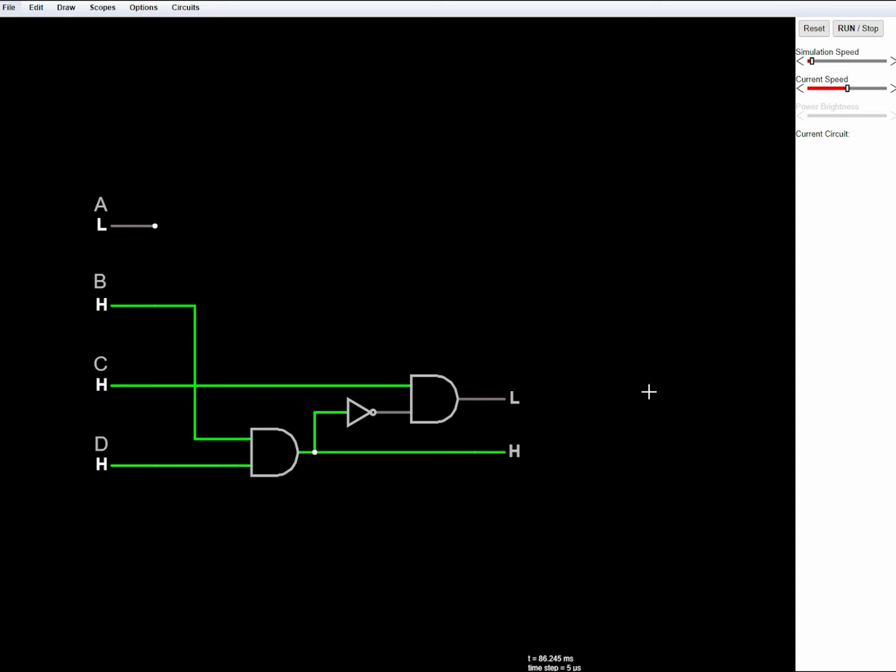In this case it doesn't really affect anything, but what if I made the assumption that both of the outputs would never be high at the same time? Or if I connected my circuit to another circuit where the output changed depending on if output 1 or 2 was reached first. That is what we call a race condition and will be the subject of a future video. But for now we'll just do a recap of what we learned in this presentation.